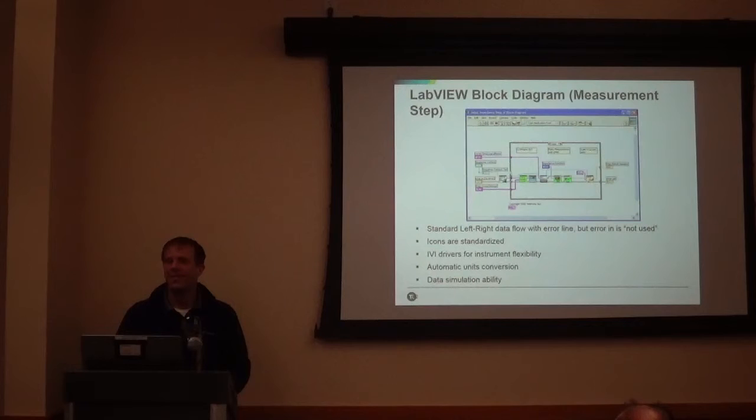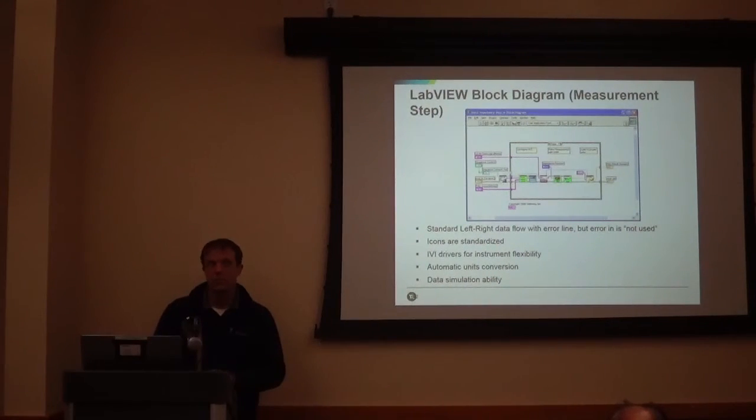For NI, like for TestStand licensing, how does it work? For every test station, we have to buy a license for it, or for the deployment? For LabVIEW, for the build model, I'll just take one license and build any application that's licensed to me. Correct. With LabVIEW, you can create infinite executables at no cost. TestStand does have a cost for the deployment license. So which license should I be having? The deployment is the lowest level, just to be able to deploy and run it. Then there's a debug license which lets you do some modification and editing, and then there's a full development license above that. That's fine. Thank you very much.